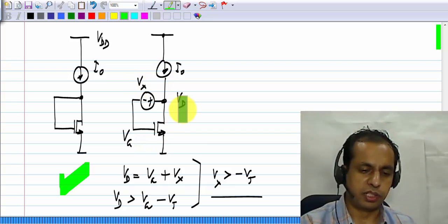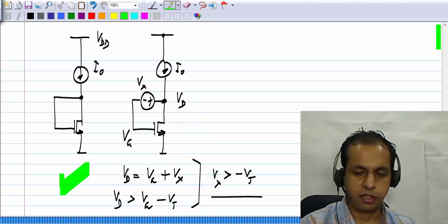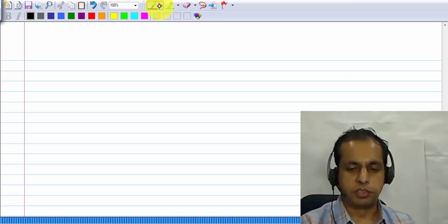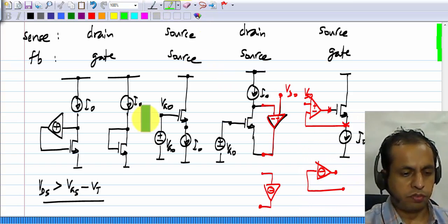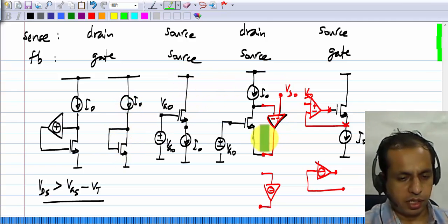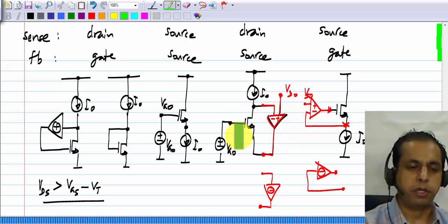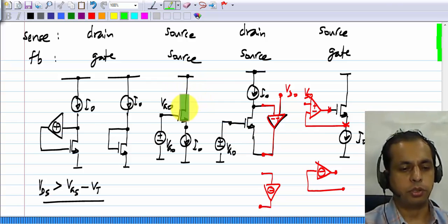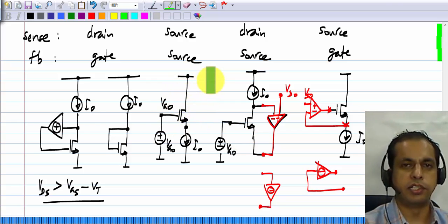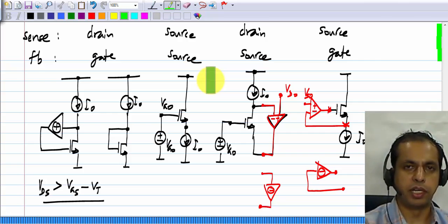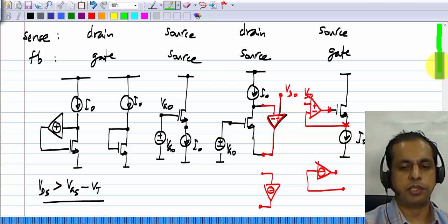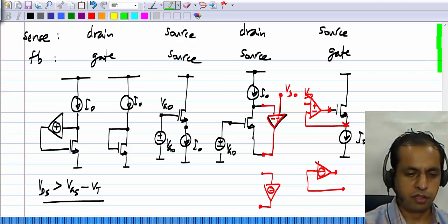Okay, so that's as far as this particular circuit is concerned, and this is true in every case. Okay, because just for biasing, for instance, in this case nothing else is connected to the drain, and so on. But when you turn this into some small signal incremental functionality, something will be connected to the drain. So you have to evaluate the saturation region condition separately. That's what I'm trying to say. Okay, the feedback has to be in the correct sense, and the transistor has to be in saturation for it to behave like a good amplifier.